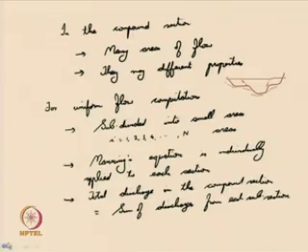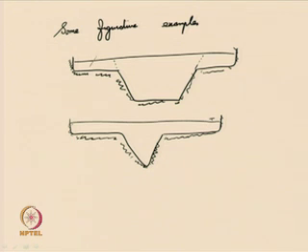If there is a difference along the flood plains of the channel, for example, again let me refer to that figure. Say here in this portion you are having a certain energy line or total energy head. Here you are having a different energy head, here you are having a different energy head. Although the water surface at this location is the same and pressure head is same, water datum is same, but the velocity head is different in all the 3 portions. So, that creates different energy levels along the different sections.